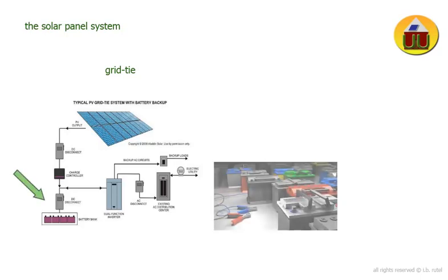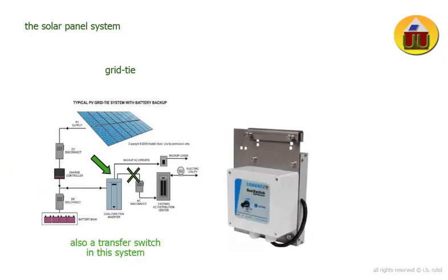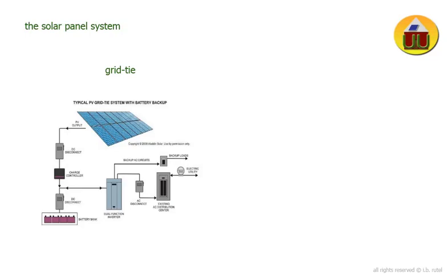However, if you want backup power, so you can keep your food cold when the power goes out, then you will need to add a charge controller, which will charge the batteries you will also need to add. Finally, there is a transfer switch, which is a safety switch that essentially cuts your house off from the grid. Now you can produce power in your system and bypass the safety cutoff in the inverter and continue to use power while the power is out from the grid, and you have the ability to charge your batteries. These hybrid systems tend to be fairly expensive because of the added cost of the safety switch and the cost of the batteries themselves.